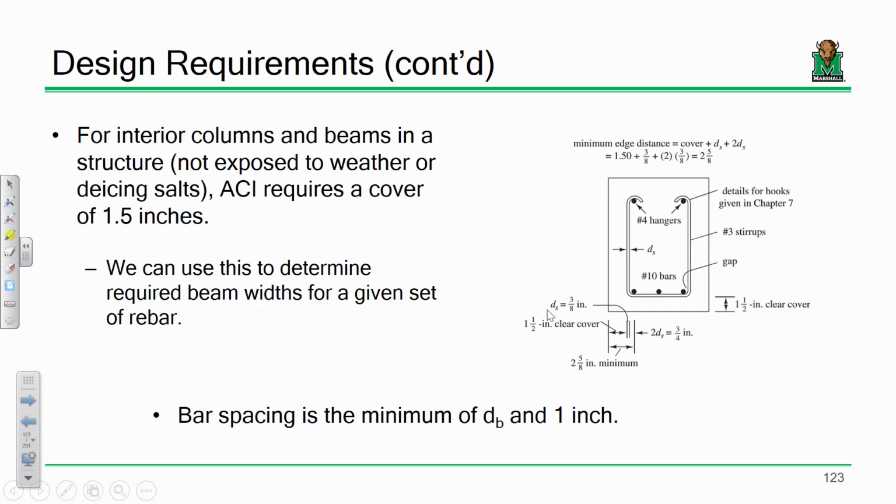So if you take 1.5 inches of cover, take your stirrup, and then take your bar diameter, which we're not sure of yet, you're probably looking at something like 2, 2.5. So just to keep things simple, a very common assumption is to take a height of D plus 3 inches, just to cover the gamut. And that's a very common assumption within concrete design.